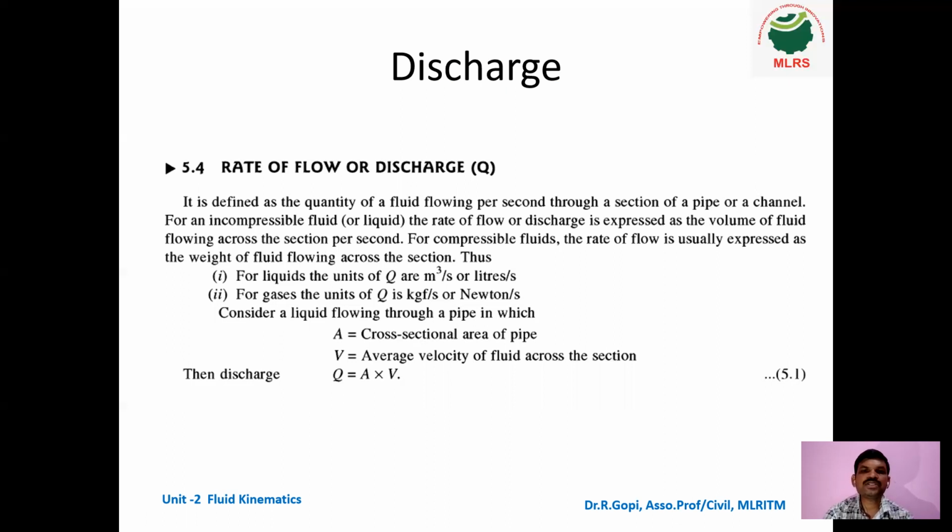The unit of discharge is meter cube per second. For 1 second, how many meter cube of liquid is discharged? Or liters per second. Sometimes in the problem they give meter cube per second or liters per second. For gases, the unit is kgf, kilogram force per second, or Newton per second, because we have to calculate weight for compressible fluids.